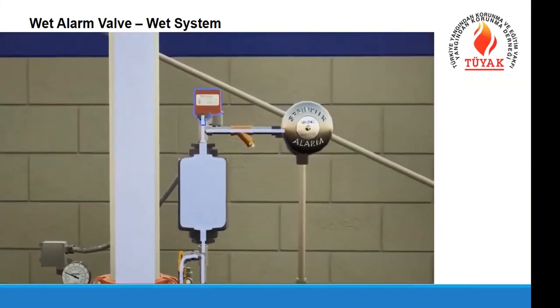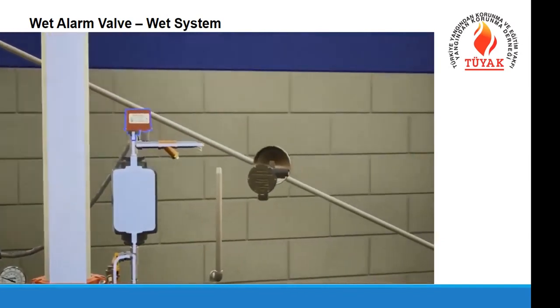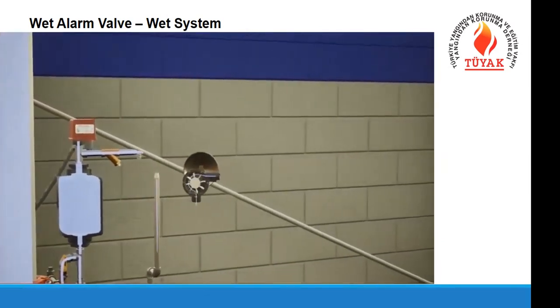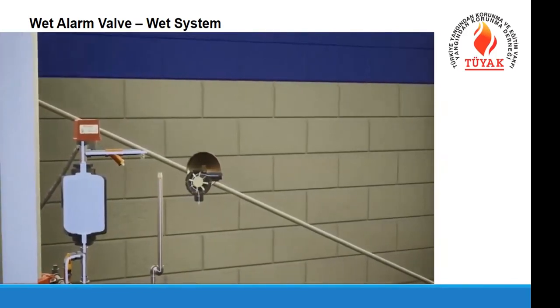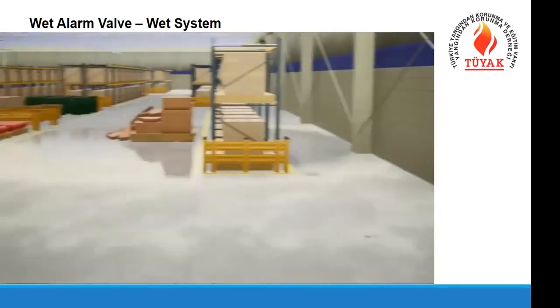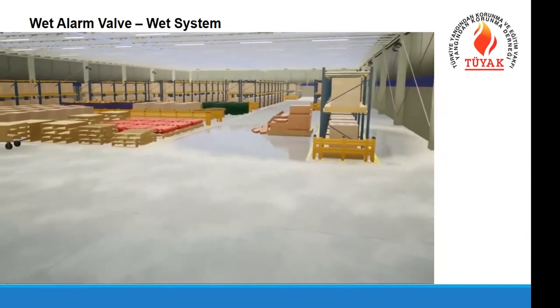The water will then activate the water flow alarm, alerting the fire department and informing building occupants to evacuate. The water motor gong is installed as a failsafe to any electrical alarms. The sprinklers continue to control the fire until the fire department arrives.